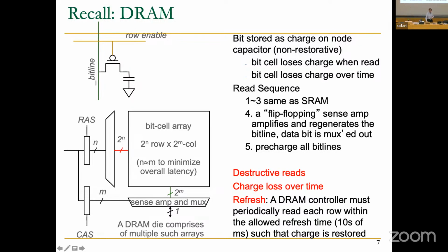But if you actually supply it in consecutive cycles, you supply n bits first and then m bits next in some other cycle. So you actually save some number of bits, some number of pins essentially. And usually these are somewhat equal, so you save half of the pins. Does that make sense? So these are design decisions that are made in memories that are somewhat dictated by technology, because you cannot manufacture this thing nicely, let's say, in a logic process that we manufacture our chips with.